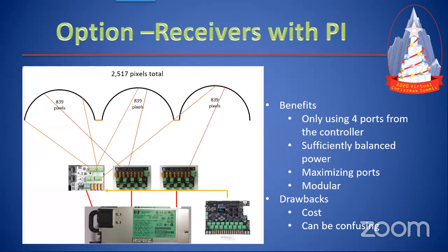This is Ralph speaking. I'm running a show together with my neighbors, and one of the differential controllers will be on their power line, and the controller runs on my power line. Would that be a problem because the two houses don't share a common ground? No, when we talk about common ground, we're talking only on the DC side, not the AC. The DC side from the controller to that smart receiver is shared already. The AC side is independent. Okay, so it will work. Yes, it will work. Okay, cool, thanks.